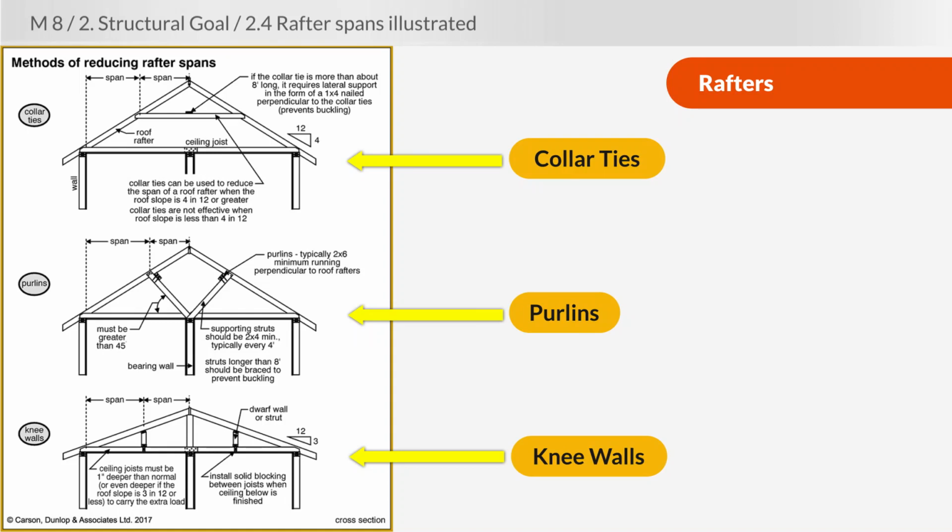It's just kind of annoying that the crack is always going to be there. You could patch it. It'll probably come back. And it's simply because the ceiling deflects slightly downward at a time that there's some extra loading placed on the roof, whether that's from wind or snow.